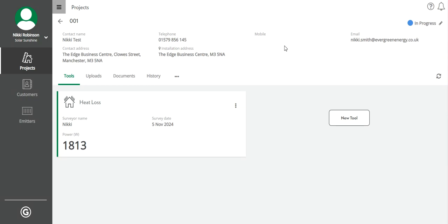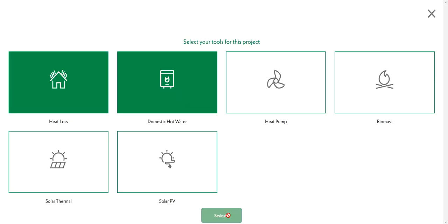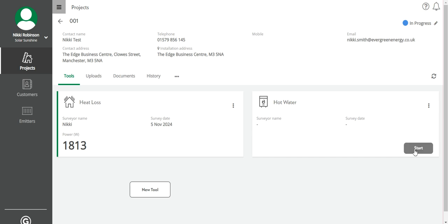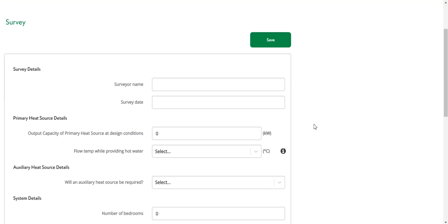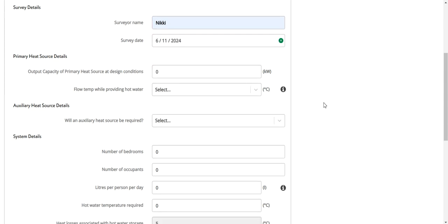So in this video we're just going to cover how to complete your domestic hot water calculations. If you don't have the tool on here already, you can just select New Tool, Domestic Hot Water, click Save and press Start to enter the calculator. You can start by putting the surveyor name and date in at the top. And then the first question asks you about your primary heat source details.